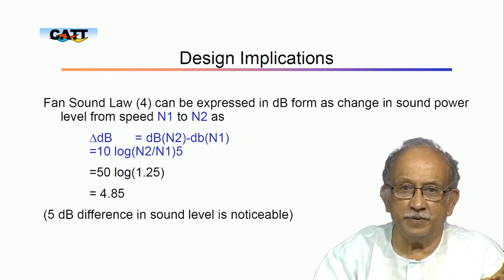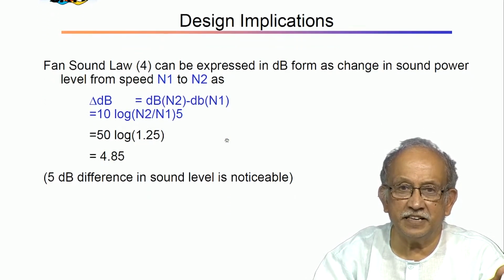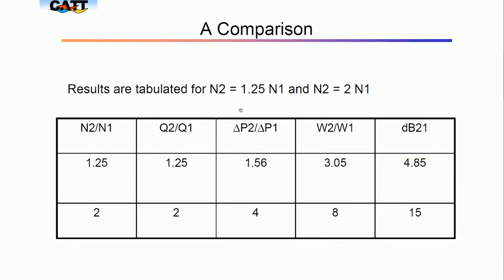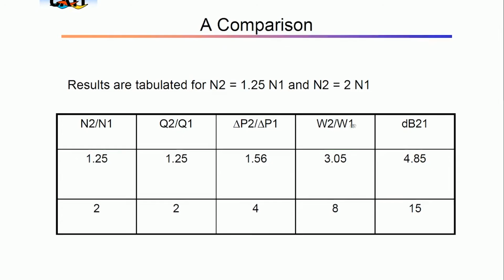So, as we keep going on, we end up with all these funnier and funnier relative nuisances. So, a big table is given here, saying what happens if you increase the speed, how much the power demand increases, and then the noise level increases, while the pressure level is just going up about double, while the total discharge is just increased by 75%.